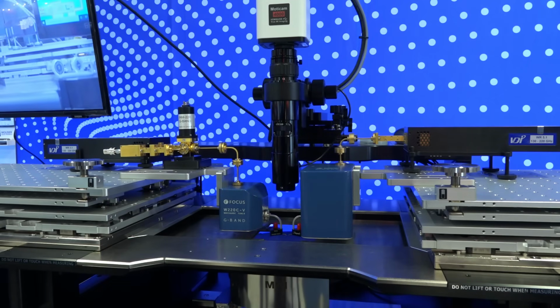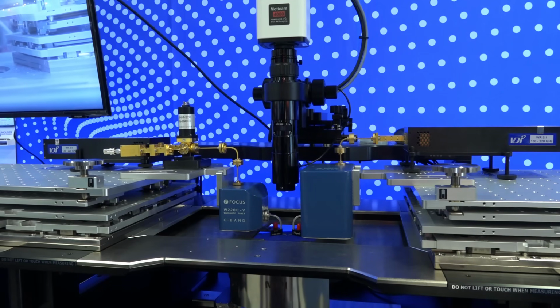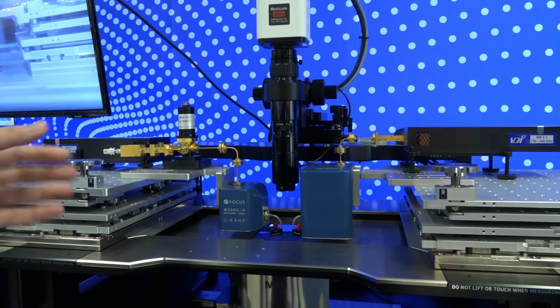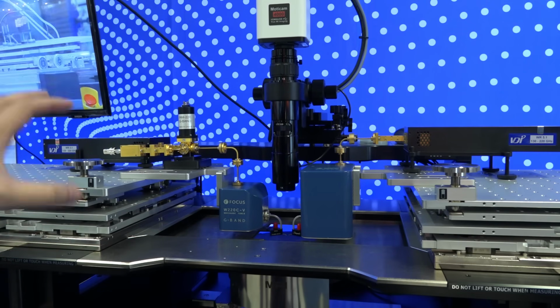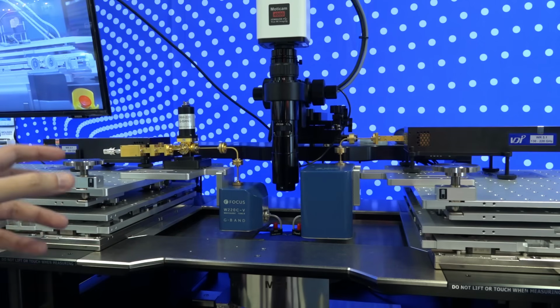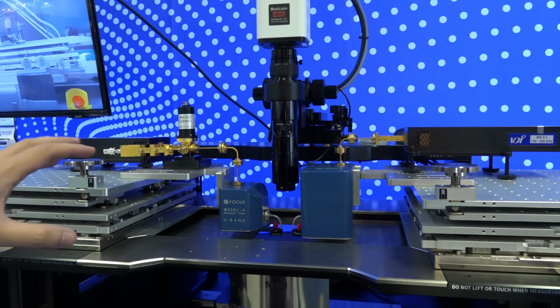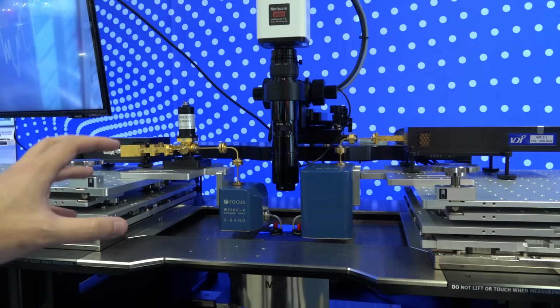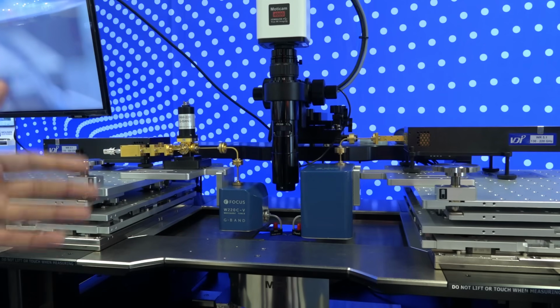So here we have a G-band measurement setup. Now, normally, a Y-factor measurement setup is going to assume a 50 ohm impedance into your device under test. It is well known that a tuner and an S-parameter calibrated setup is going to give you significantly better repeatability and precision of noise figure. But that's always a pretty difficult thing to do at higher frequencies, especially at G-band.